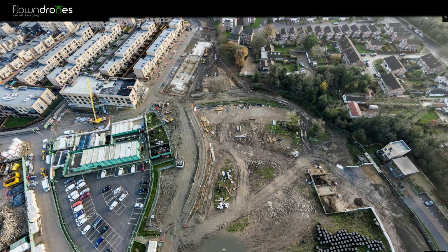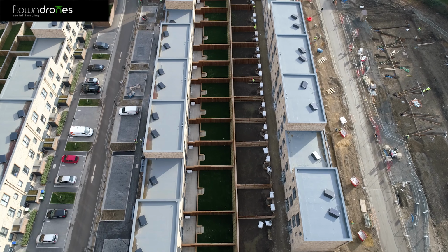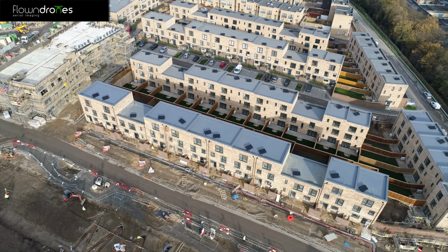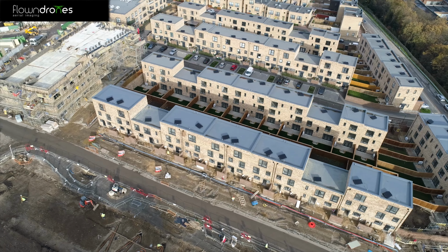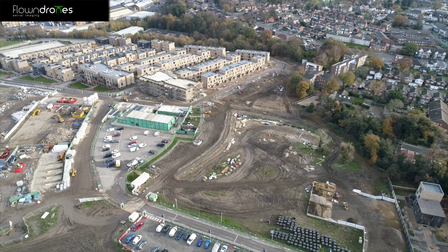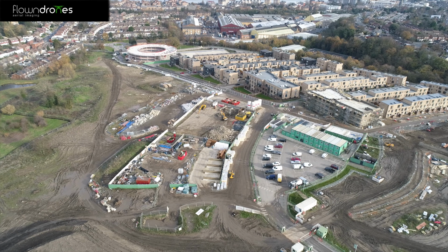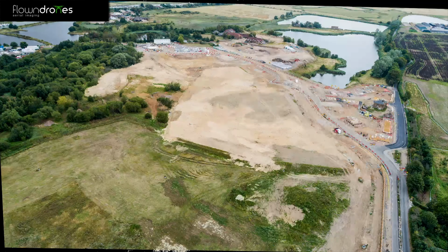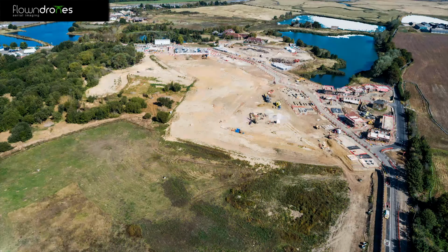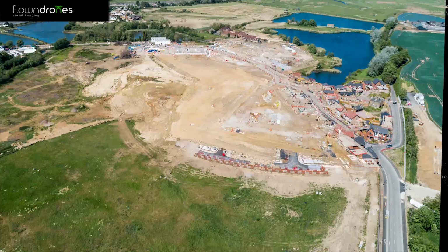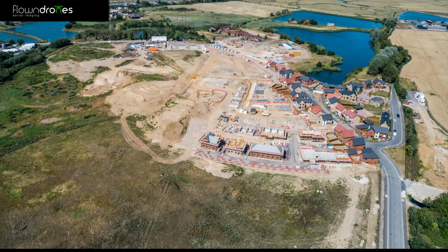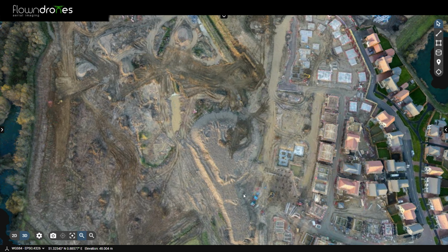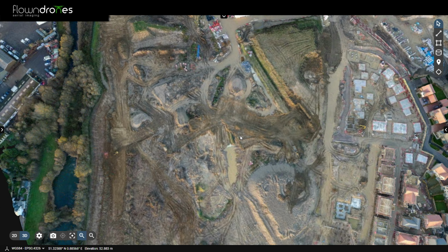And then we can also offer aerial photos and video. We're able to take the drone back to exactly the same GPS coordinates and height, the same yaw angle, which is the angle the drone is facing, and the camera pitch angle, which allows us to create exactly the same photos every month and offer almost a time lapse. The lighting conditions need to be similar for that to look like a time lapse, but it can give you a good progress report, taking photos, repeating the same angles.